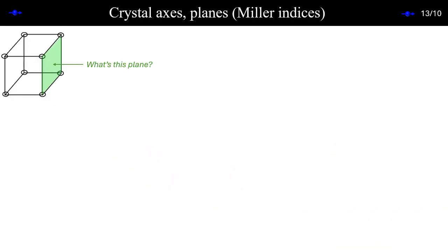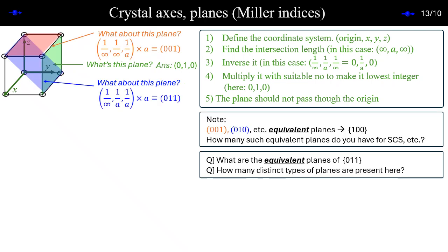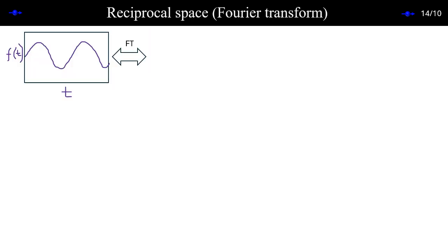And when we have planes, a crystal structure will have planes. We need to define planes, called Miller indices. We will discuss different types of planes. Here we have a periodic arrangement of atoms, right? For electrical engineers, when you see periodicity, you become excited because things are related to Fourier series or Fourier transform. For a lattice, the same thing is applied. If you do the Fourier transform, it goes into reciprocal space, because a lot of times a different viewpoint is important. You should have both sides.